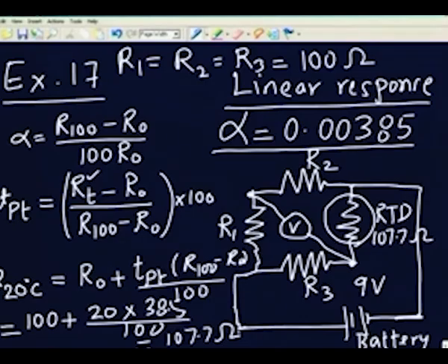Now, let us look at this circuit here. There is a 9 volt between these 2 points, let us say A and B. Between A and B there is a drop of 9 volts, and there will be 4.5 volts drop across this and 4.5 volts across this, because it is equally shared among the 2 resistors in series.